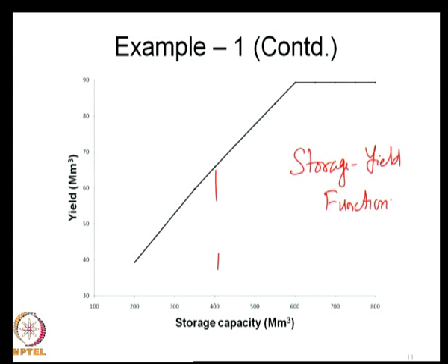As you can appreciate now, both these are planning exercises, where we are thinking about building a reservoir, and then asking what kind of capacity you need to build. Even with the storage yield function, you are saying that if I build a reservoir of 200 units, then what is the type of constant demand that I can meet. If I make it 400, what is the constant demand that I can meet. So, the storage yield function is also typically used for planning purposes.